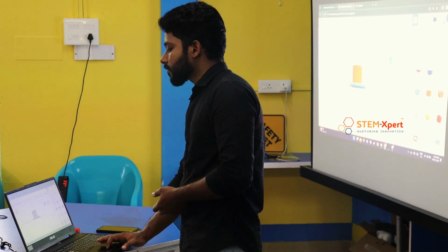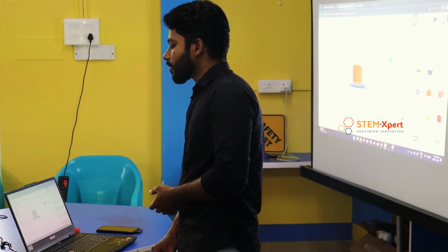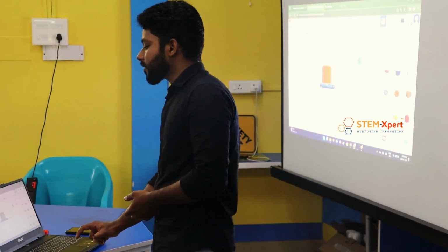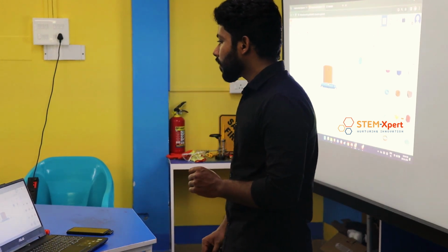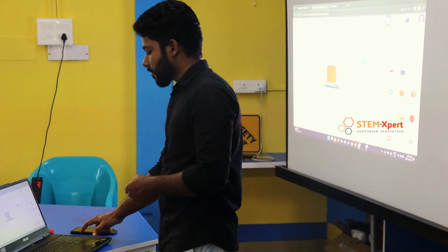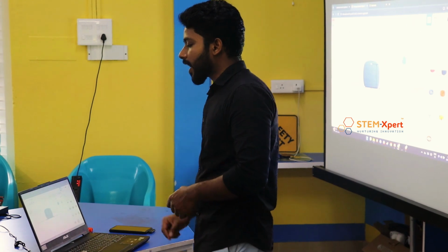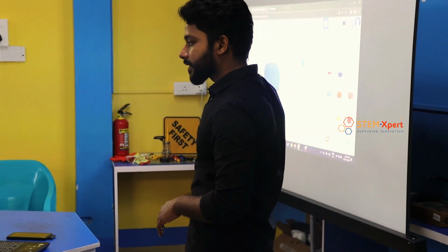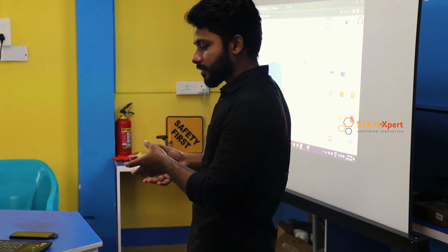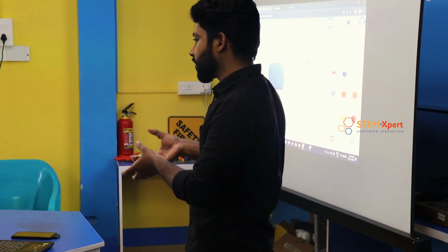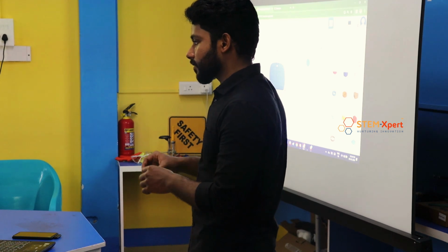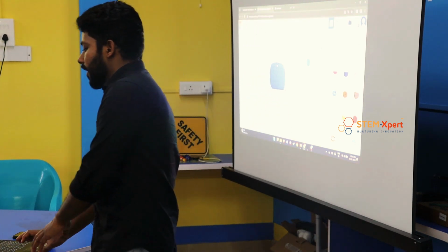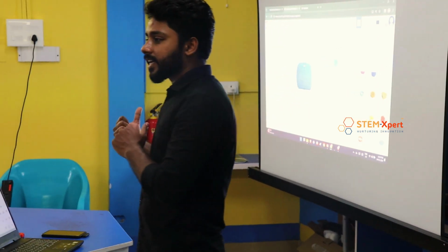Front view. Then click on to this point. Here we will be changing the dimensions to 35. Okay, 35. We have used the 40 as dimension for the cylinder, right? So now we are changing the dimension a little bit for this torus. Okay. Anyway, we are going to make this object as a hole object, right?